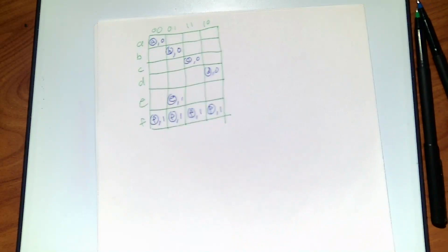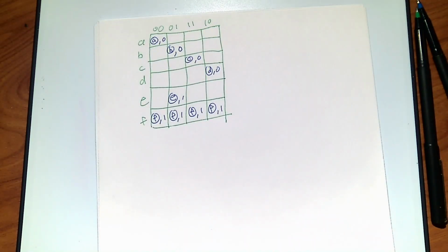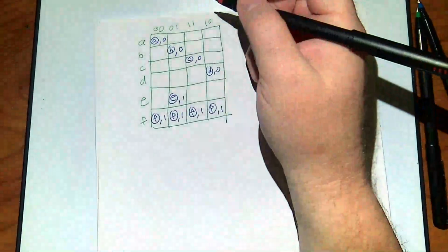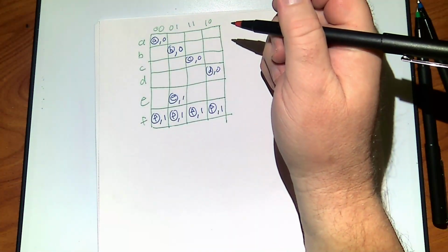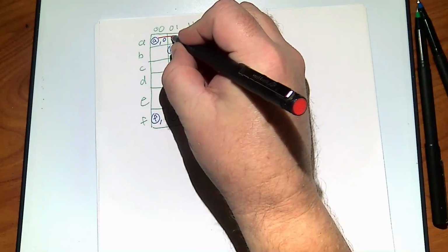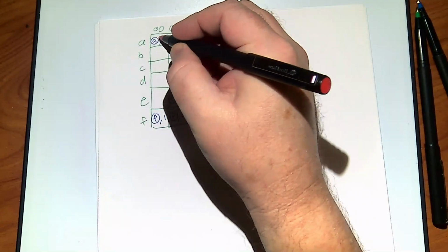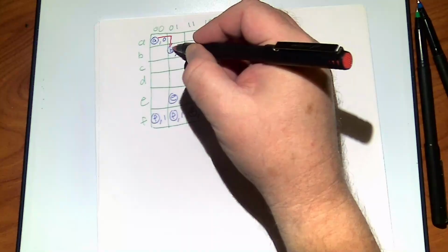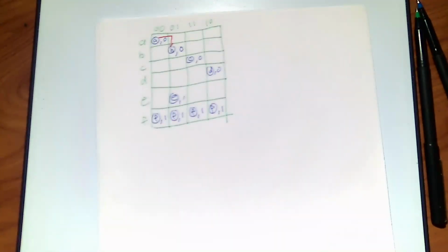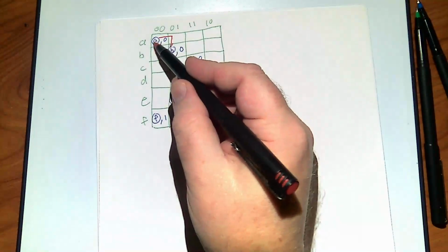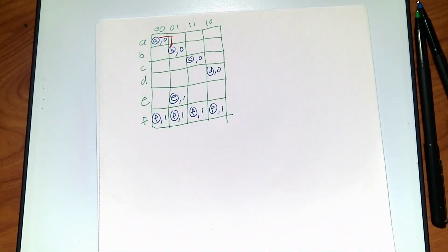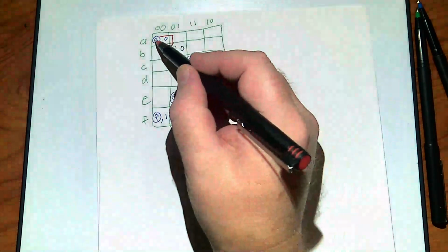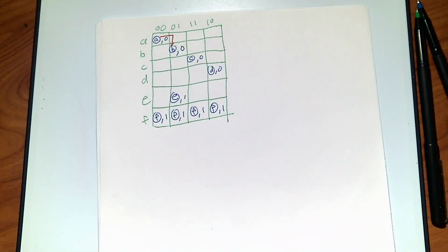Now, what I'm going to do, I'm going to keep a lot of different colors. Let's see, okay, I got red for this one. When I draw my transition arrows, I'm going to always draw them going over first and down. So if it goes from state A to state B on a 0, 1, I'm going to draw it from, I had to have been in my stable spot, because otherwise it's too likely to just randomly happen. And I'm going to do the horizontal first, because in theory, I was sitting there in my stable state waiting forever, and then an input came in and I reacted.